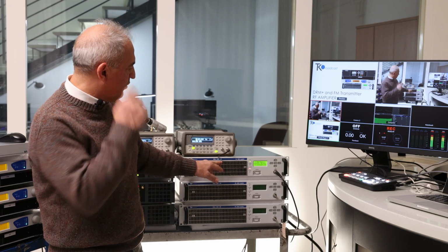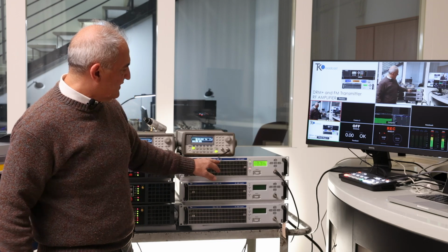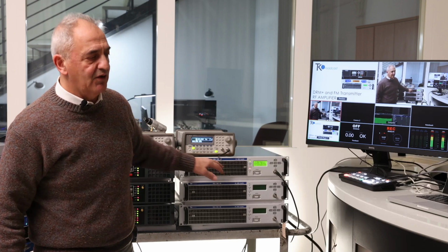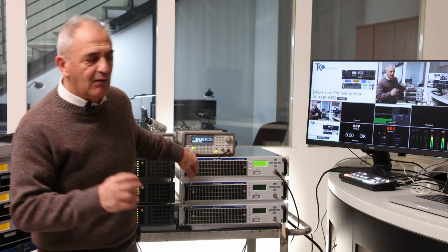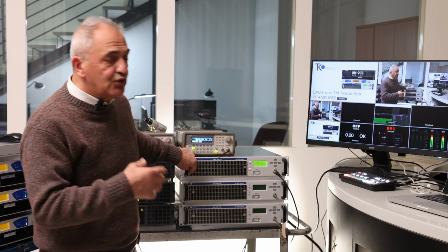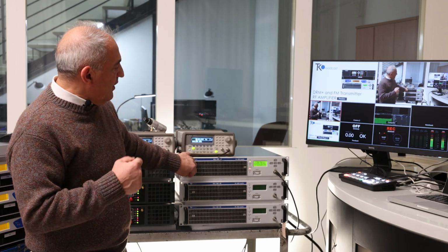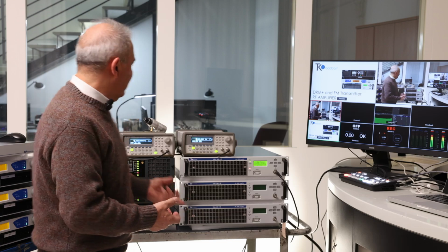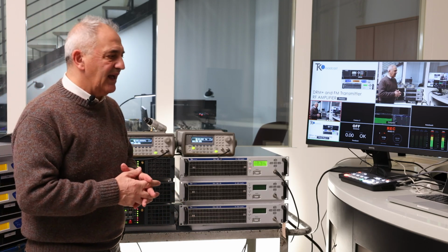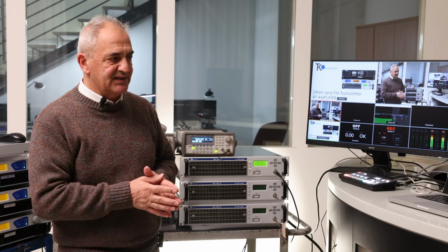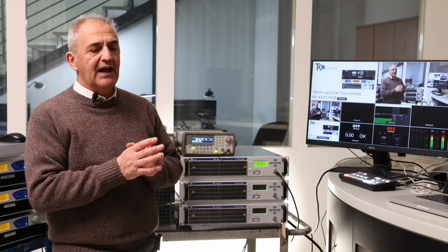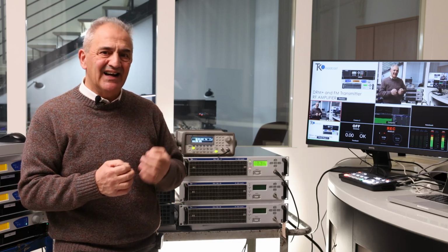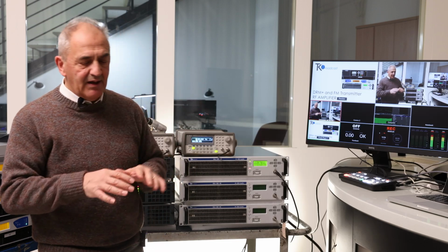For this reason, this one is called Cell 1200 HD, because it has the possibility to switch to digital and work in linear class. But more than working in linear class, it needs to receive a signal that can be pre-corrected by the exciter, because even the most linear amplifiers on the market are not able to create such a linear amplification as to keep the intermodulation products at a good level.